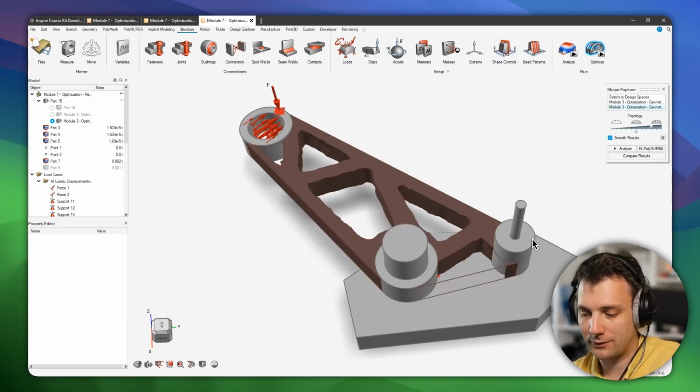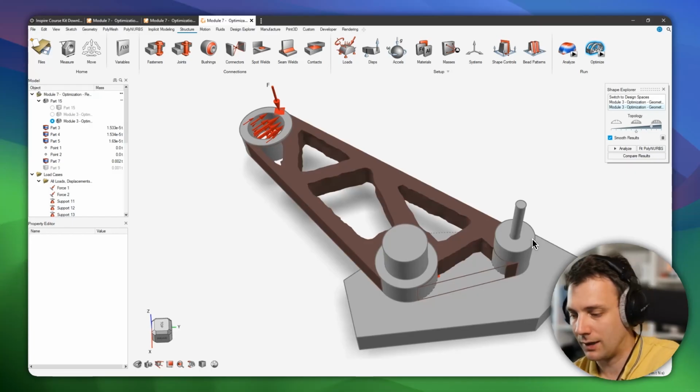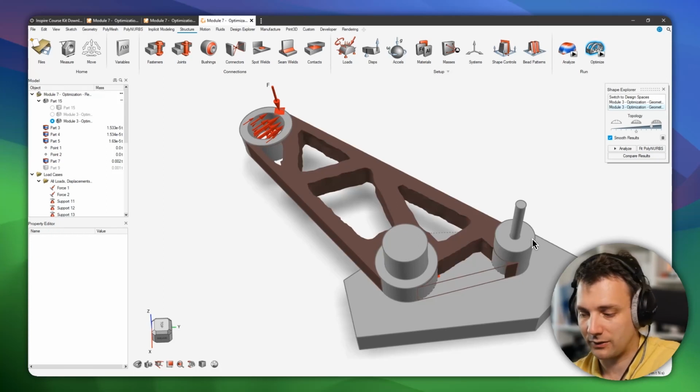Experiment with the model, and you can see that's also why I like topology optimization this much. You can experiment and just explore the design space and see what makes sense, what doesn't, and come up with other ideas, other constraints, other load cases especially, and come up with a solution which is even better than the one before.